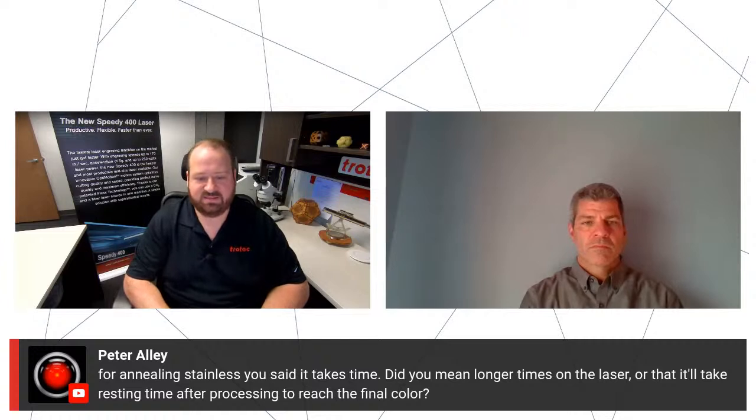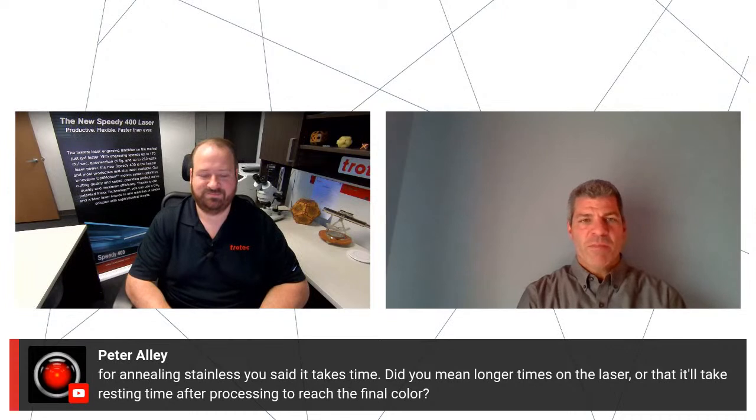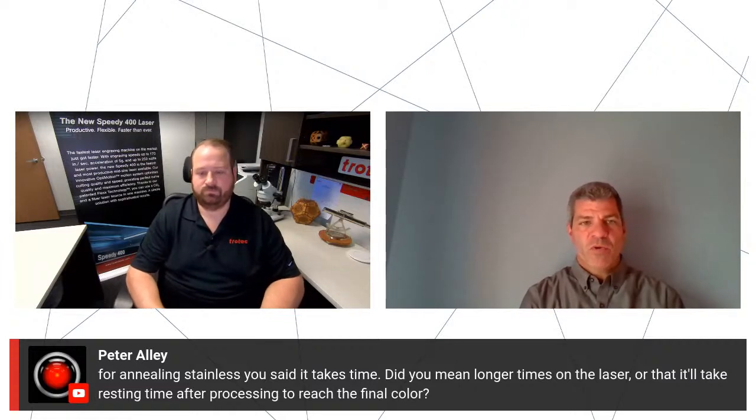For annealing stainless, you say it takes some time. Do you mean longer times on the laser, or the time it will take resetting the laser after that to reach the final color? Andy, maybe a good one for you, since you're really good on the Galvo side. Yeah, David was referring to the amount of time it takes to create the marking. It does take longer to create that annealing. There's no resting period required.